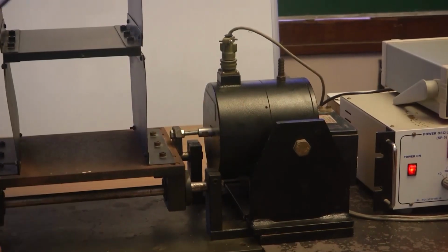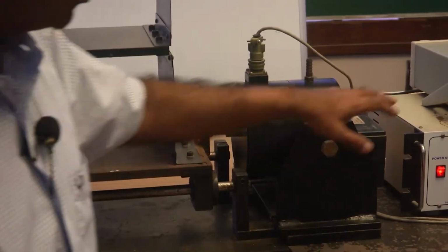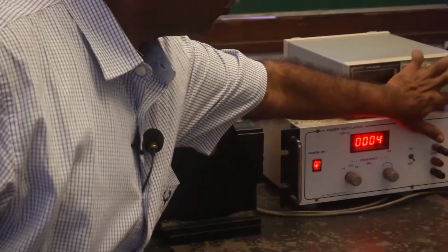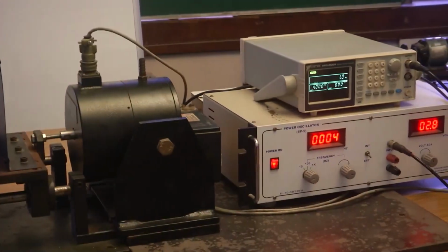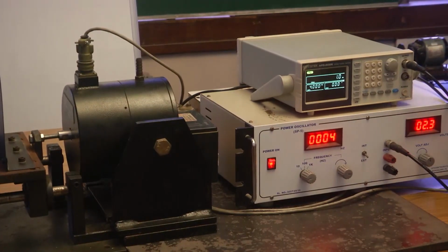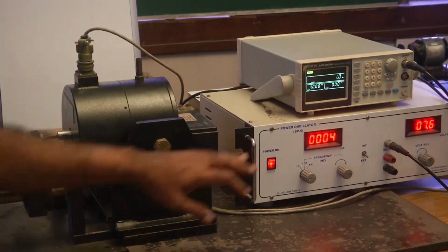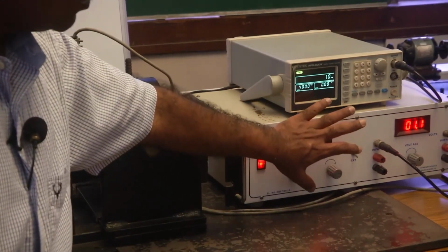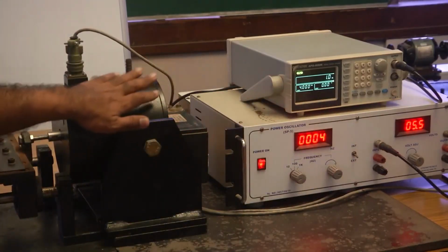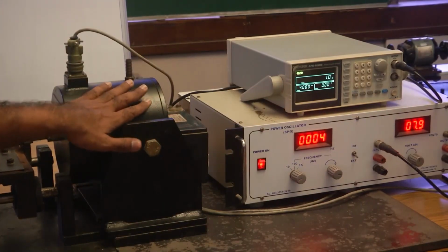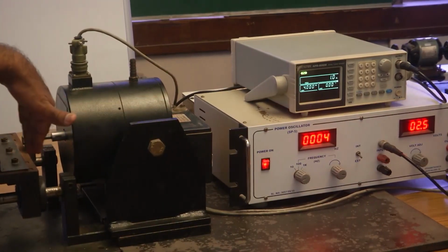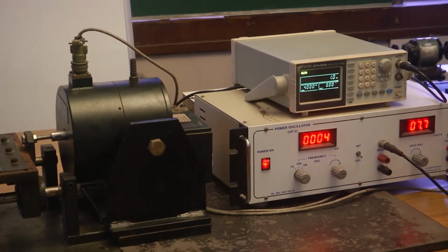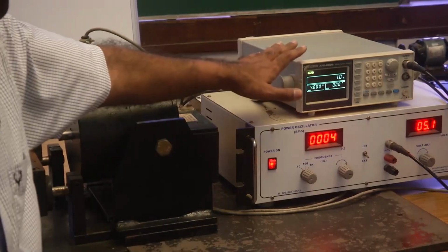Now, for that purpose, what we are going to do is to use a signal generator here, which is going to generate an electric signal of a given frequency and amplitude, which of course will get amplified using this power amplifier, and the amplified signal is fed to the electrodynamic shaker, so that the shaker oscillates or moves the base plate back and forth at a given frequency. And so that is how we have done here.